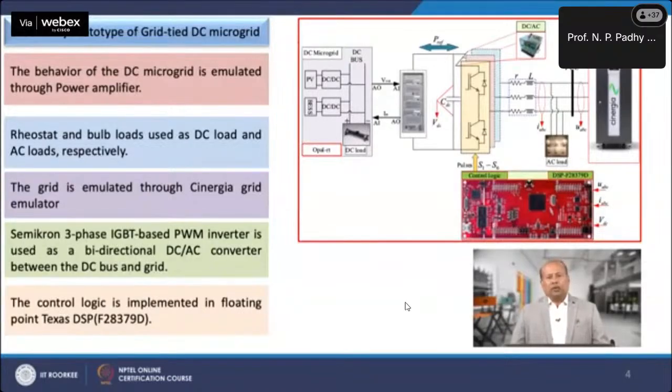The control logic shown in the previous slide is implemented in the DSP controller. The floating point Texas Instruments C2000 DSP controller of the TMS320F28379D Delfino type is used in this hardware test bed.